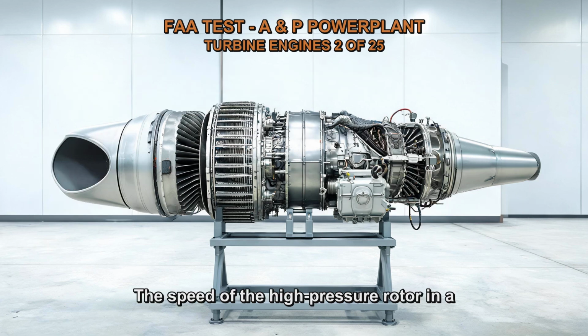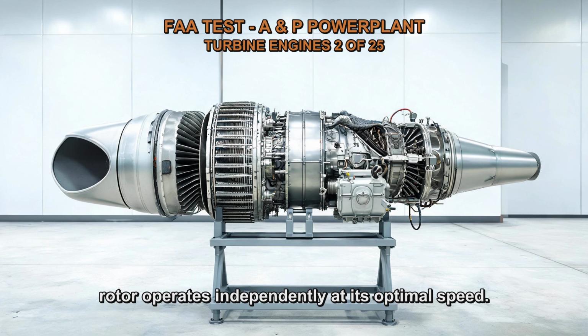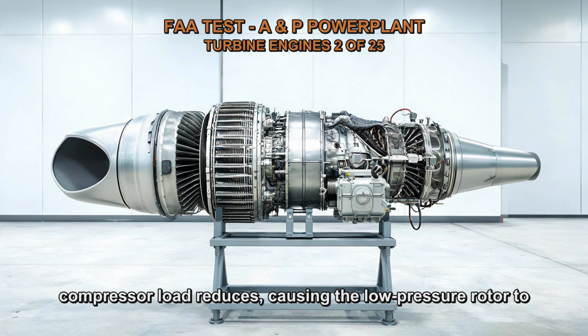The speed of the high-pressure rotor in a two-spool, split-spool compressor is controlled, while the low-pressure rotor operates independently at its optimal speed. At higher altitudes where air density decreases, the compressor load reduces, causing the low-pressure rotor to accelerate.